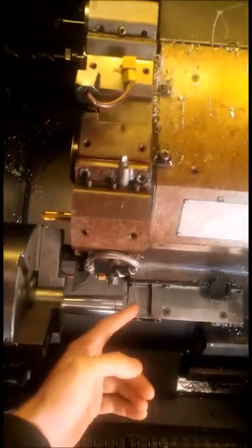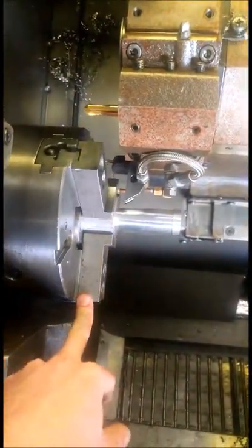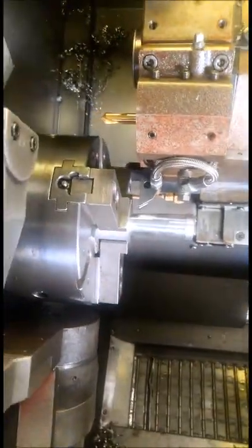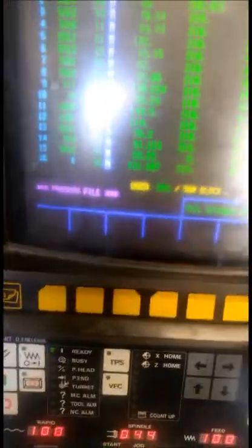And then jaw data number. You can have different chuck jaws drawn into it. Say you had some big elaborate chuck jaw that stuck out really far and you needed to machine up really close and your tools were going to be coming close to it, it'd probably be important to have that drawn up. Most of my soft jaws are pretty basic, and if I'm going that close, I'm pretty careful about it anyway, so I don't bother drawing the chuck jaw shapes. I just use number 1, which is already in there. Tail spindle length doesn't matter. I'm not using a tail stock in this, and actually I've never used that. So that's it for the program setup.